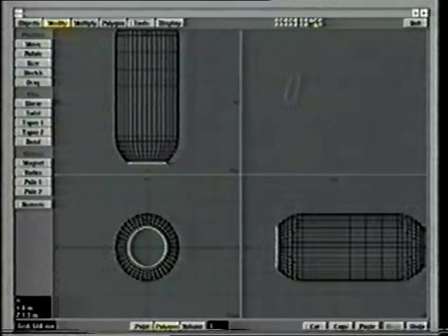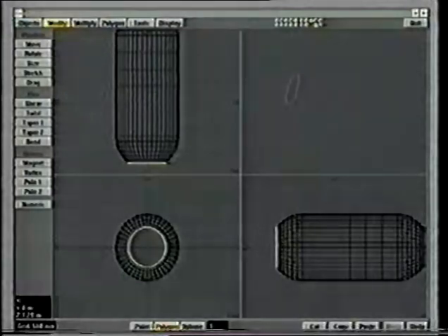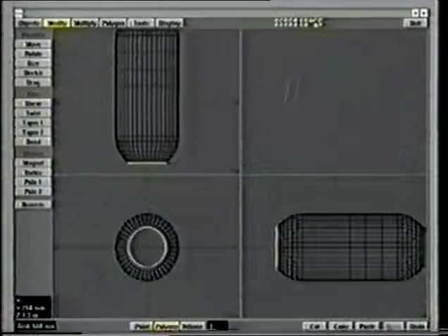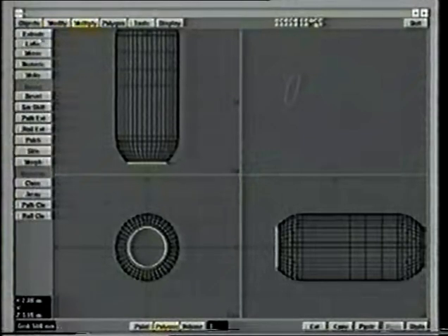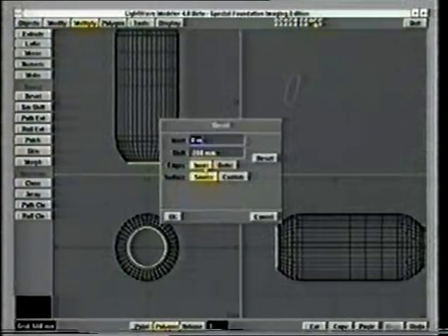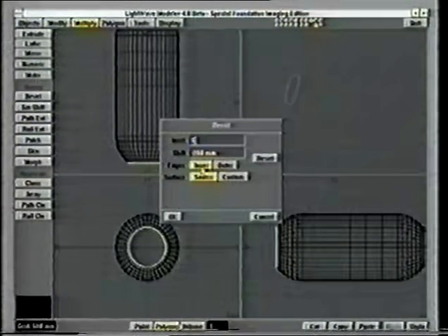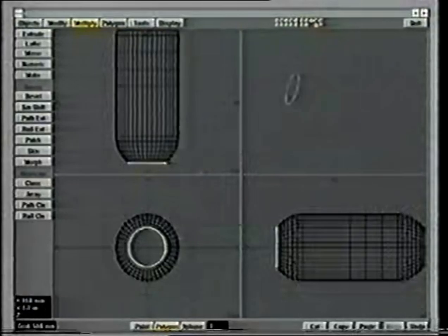So now, as we're going to be recessing this hole in the front of the gun pod, we've got to be cognizant of which way the polygon is flipped to make sure that the inside of this is going to exist as opposed to the outside. So when you're extruding it or beveling it, you need to always bear that in mind. So again, we'll do a bevel on this and say an inset of 10 millimeters and a shift of 0. Okay, there's our lip.